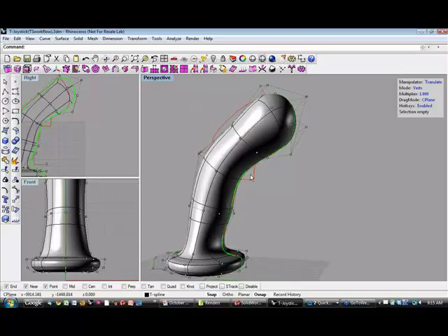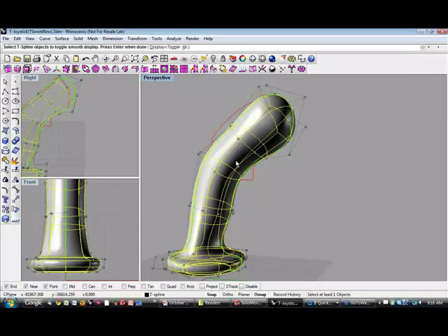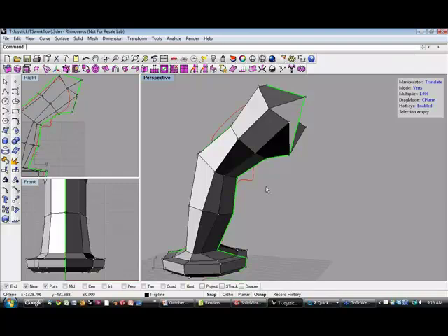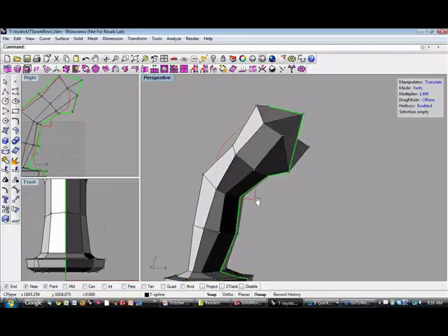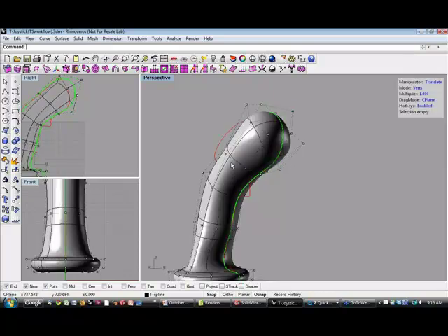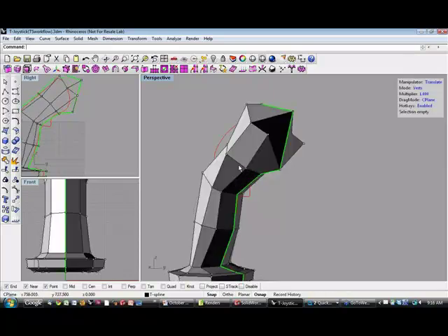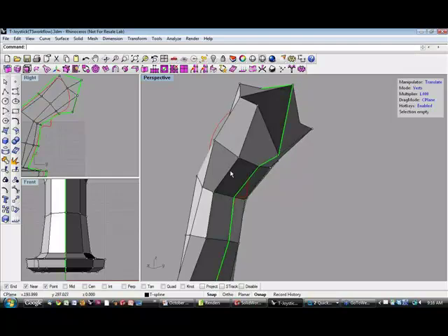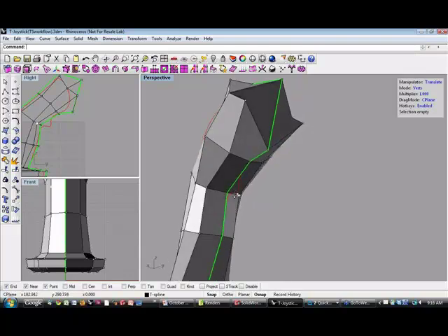And anytime that I'm adding and deleting faces from the T-spline, I like to switch modes. This is what we call the smooth T-splines mode. We also have a mode that we call box mode. So you can click the smooth toggle icon and select the T-spline surface, and you can see how it now is represented as a boxy mesh. It's still the same model, and the control points are in the same locations between the smooth surface and the boxy mesh. But this just gives me a little bit easier way of understanding the topology of my model and where all the faces and edges are located.